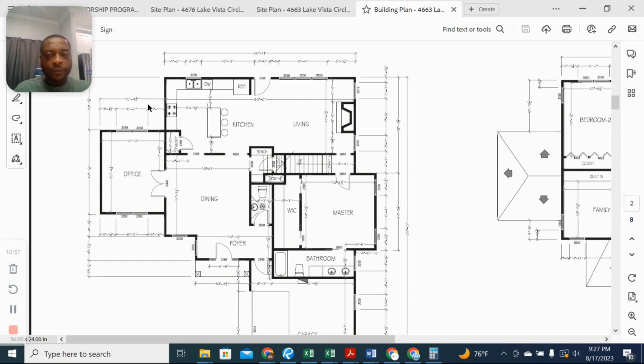If you recall, we said earlier, based on the site plan, so long as we were under 65 feet or within that margin, we're good. So at 53.5 feet, we're definitely good. Okay, you follow along? So from here to here, we're about 53.5 feet. So we're far within our boundaries of the 65 feet.